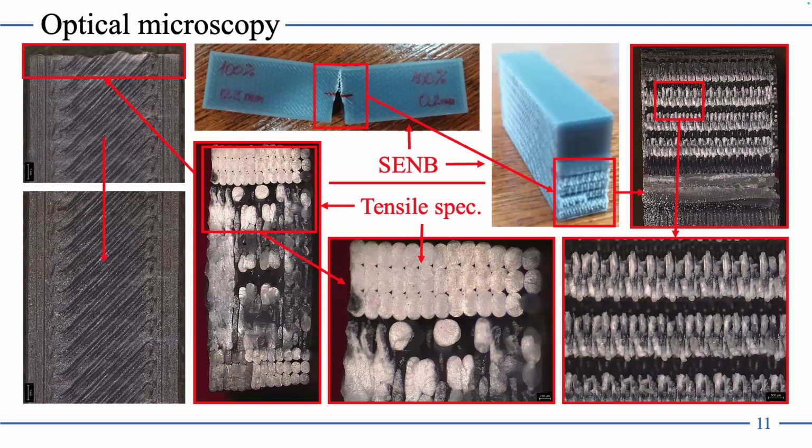So this is the main problem with all the commercial FDM printers. I'm not sure about the industry grade printers, but this is the main case, and this will create problems to actually measure exactly as it should be the delta A. Because you'll have jumps, and you see from the more zoomed image, these voids are like the center of the hexagon.